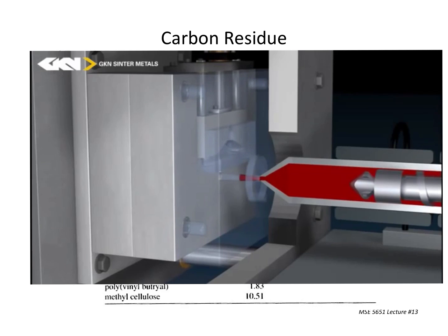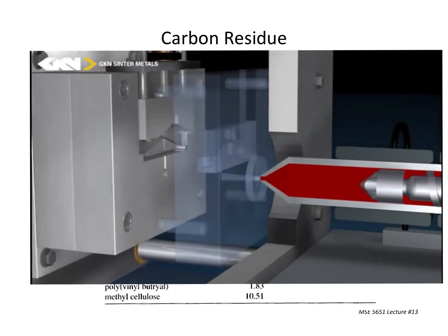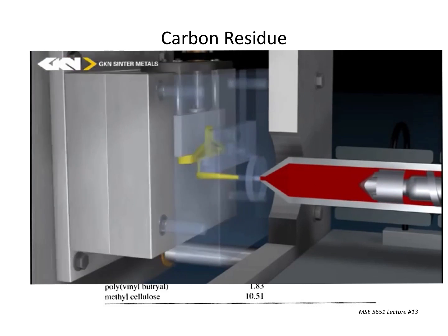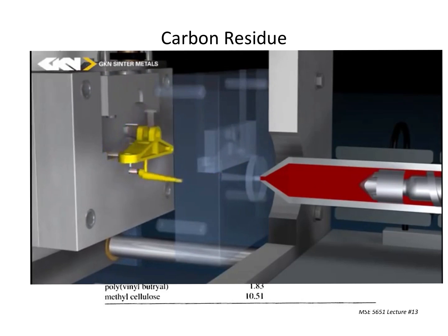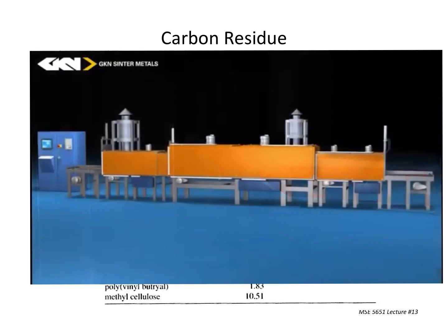So then injection mold the darn thing, this part is made, and we talked about how long this takes previously, a couple of seconds to actually make it. Everything else can be much longer than that. And then this is popped out, and you see the runner and the gate material that has to be separated from the part itself, and the process repeats itself as quickly as possible. Just trying to make money. And again, as you saw, you could have 2 of these being made at once, you could have 6 of them being made at the same time. Really, more than 1 at a time.